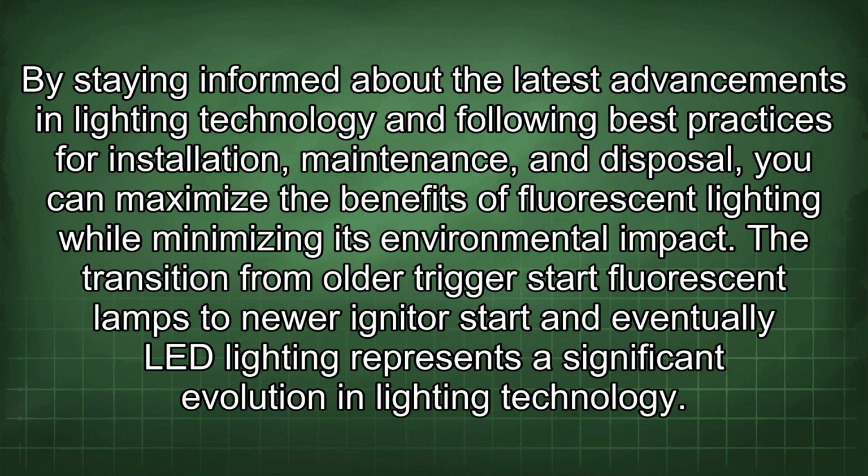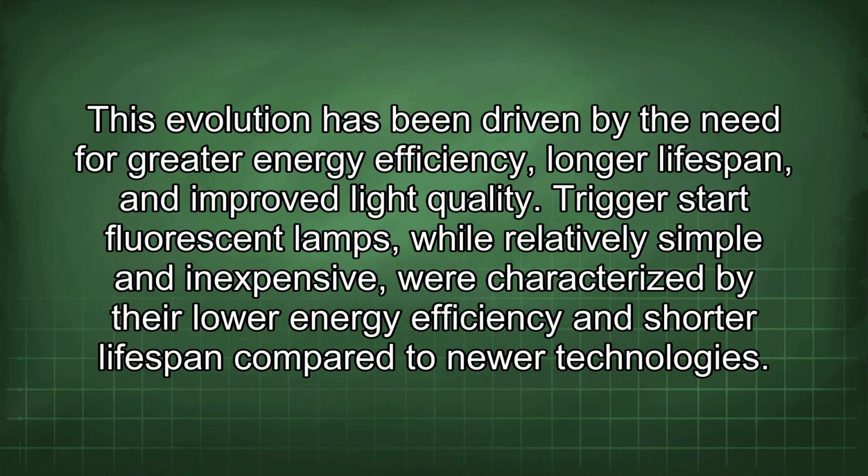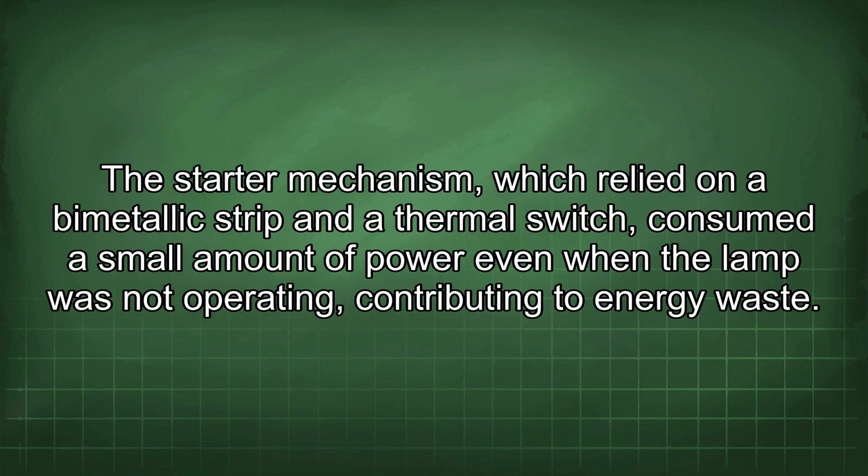The transition from older trigger-start fluorescent lamps to newer ignitor-start and eventually LED lighting represents a significant evolution in lighting technology. This evolution has been driven by the need for greater energy efficiency, longer lifespan, and improved light quality. Trigger-start fluorescent lamps, while relatively simple and inexpensive, were characterized by their lower energy efficiency and shorter lifespan compared to newer technologies. The starter mechanism, which relied on a bimetallic strip and a thermal switch, consumed a small amount of power even when the lamp was not operating, contributing to energy waste.